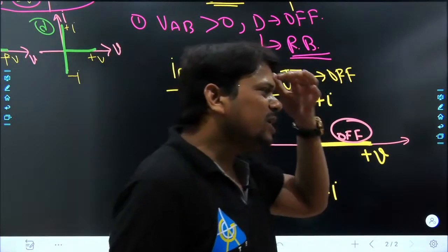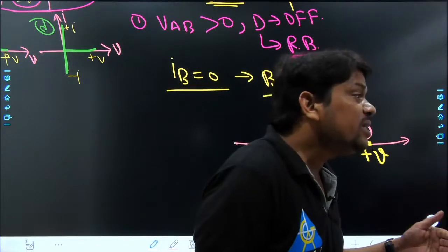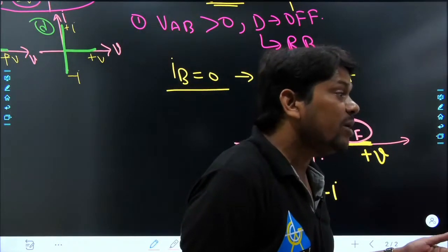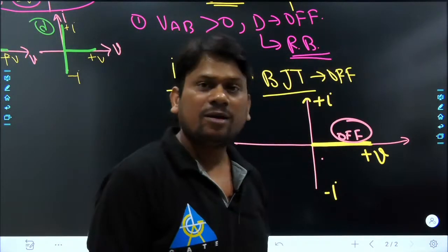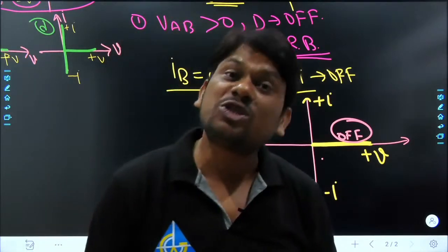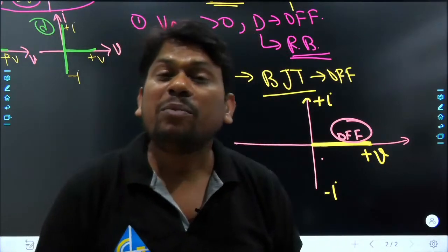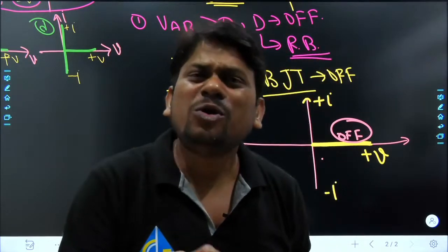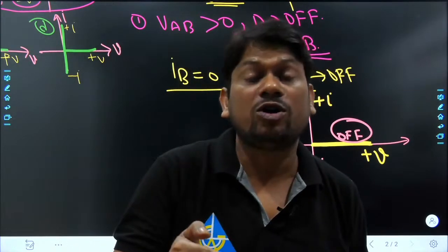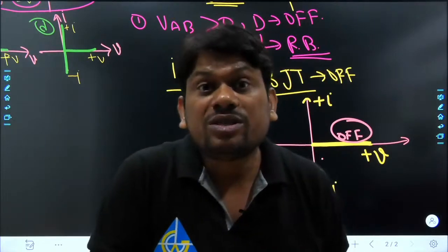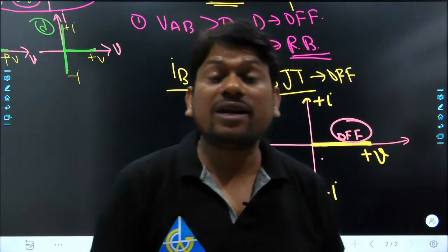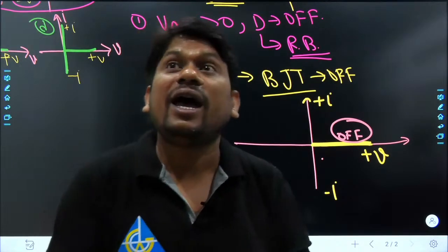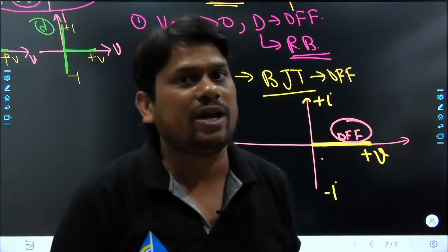Sir, one silly question, why do we use a PN junction diode, not a Schottky diode, in the switch module? My dear friend, we can use a Schottky diode, but only for very low power rating, not more than hardly 100 watt or 200 watt. That's why Schottky diodes are so popular in analog circuits, not in power electronics.